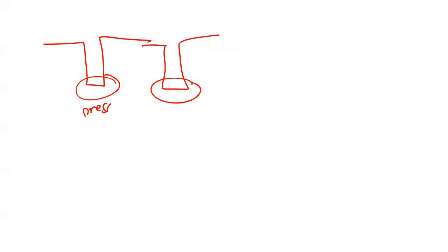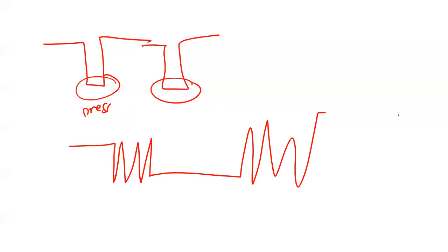What happens is that you press only one time. You actually press one time. But because of the bouncing, the microcontroller is going to assume you did one press here, one press here, one press here. So you only press one time, and the program has to take action only one time. You understand? Every time I press one time, you have to take action one time because it's one press. But actually, because of the bouncing, you press one time, but your program is going to behave, or take 3 actions, 4 actions. Your program would think you pressed 3-4 times.